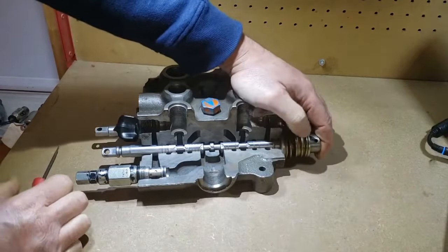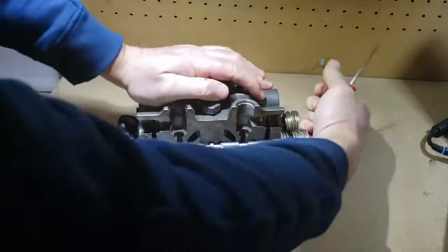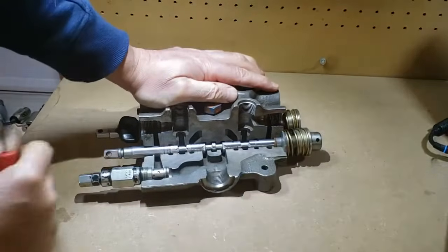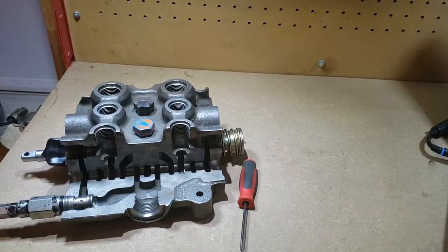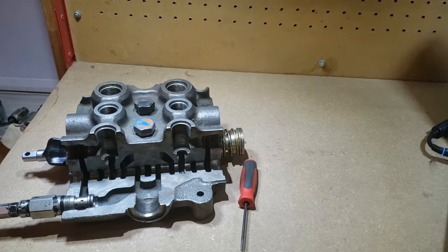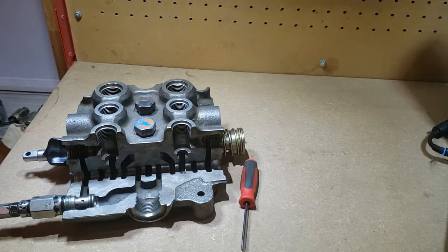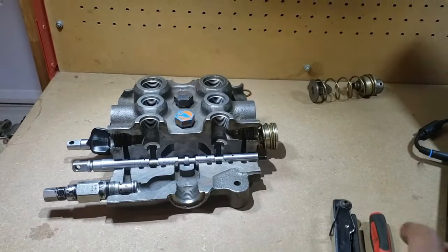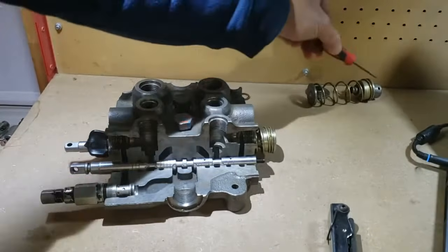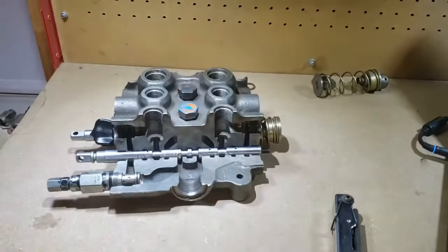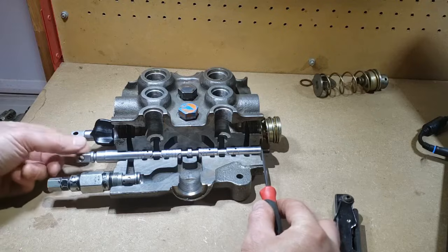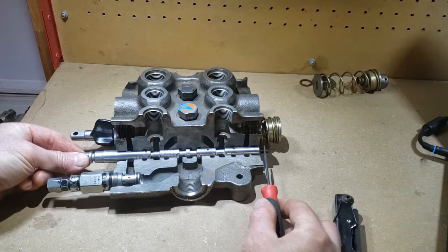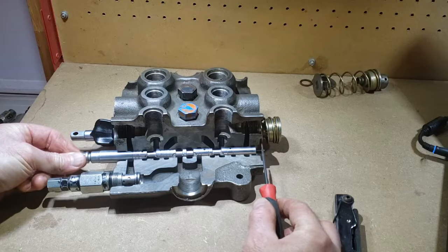In the raise position, what happens is the open center flow path, I fight the centering spring here a little bit. Just one second. I'm just going to get rid of this centering spring here so I can move this spool back and forth for the demonstration. Okay, so I just unscrewed the centering spring on the cap where the detent balls for float would normally sit. Seal there. So that's where the spool would sit in the hold position when the spring is centering it there. If I move into the raise position, that's about here.